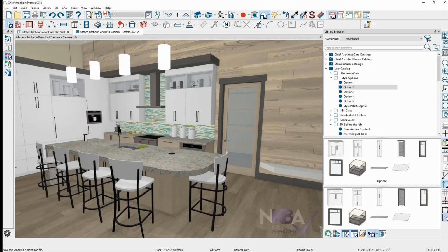If I had saved the plan, I can't undo it. So if you save the plan after you did that, undo won't work, but depending on how long you've been working on it, you can pull that plan out of your archive folder. Are you familiar with your archive folder? Our typical archive, once you save a plan, archives it, I think our default is every 5 minutes. Yeah, I've done that before.